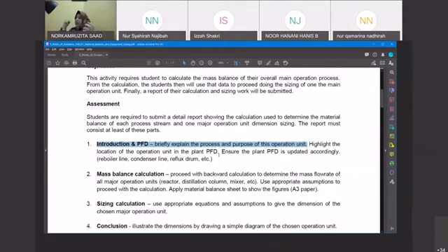You need to have 1,000 kilogram mole of product at your distillate. So now, how much feed do you need to make sure you have for your column? You have to figure out how much feed gives you that amount of product. So you have to go backward.